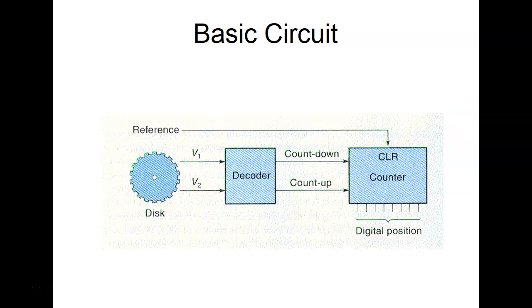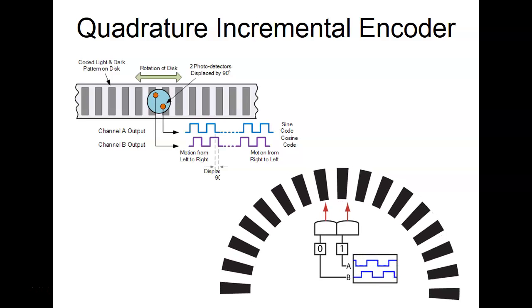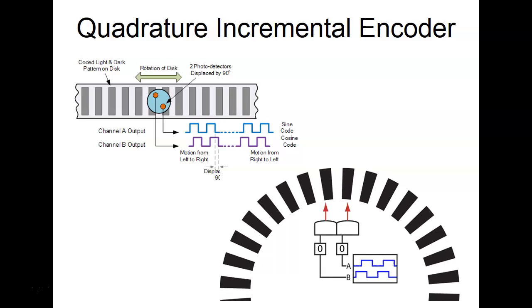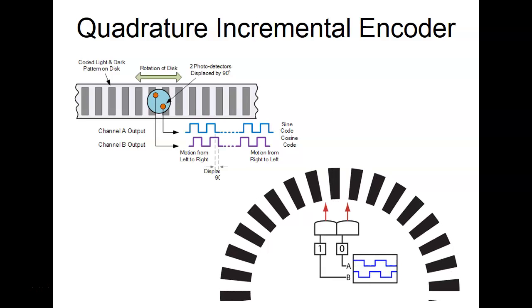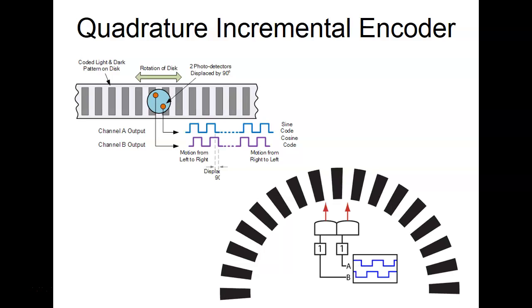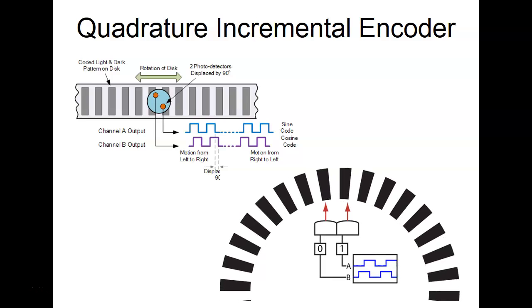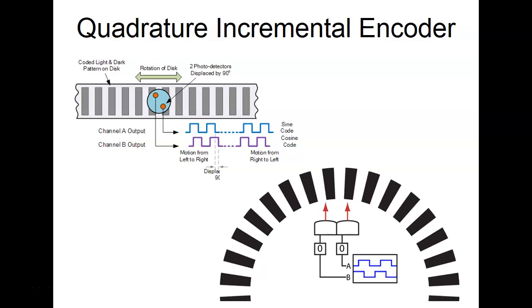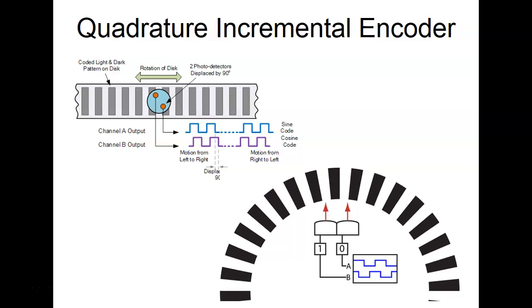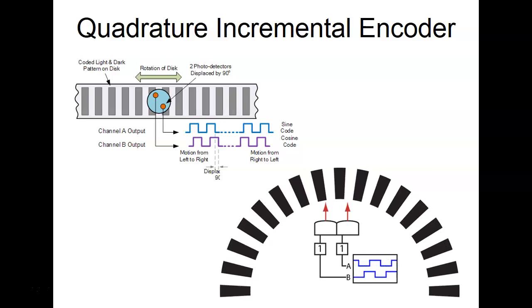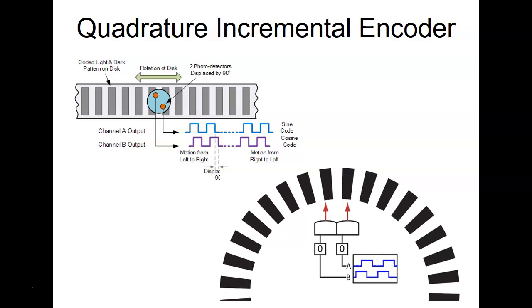But you've got to understand, we can use these incremental encoders for two different things. Not only can we use them to sense position, but the rate of the pulses could also tell us the what? Starts with an S. Speed. So this is a big advantage of an incremental encoder. It serves two functions. On a robot, especially if you're doing a control path move, you not only specify a position, but you specify a speed. It's no big deal because they can get the speed off the incremental encoders too, right? Because of the rate of the pulses. So incremental encoders are really, really popular out there.